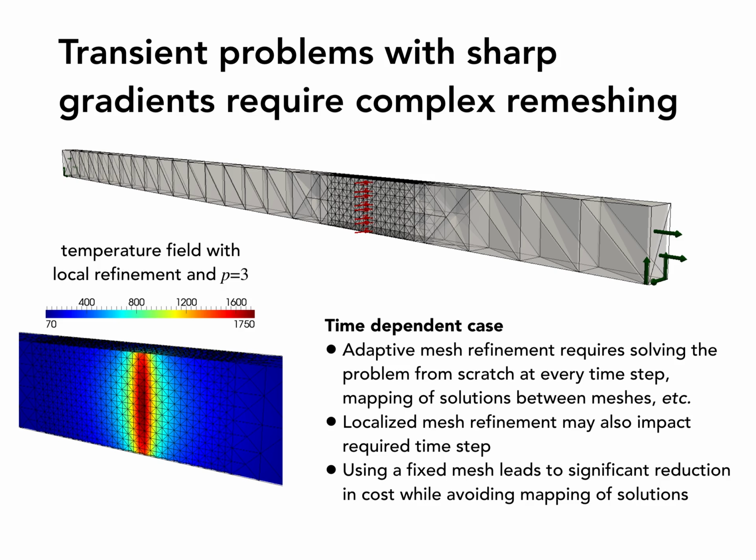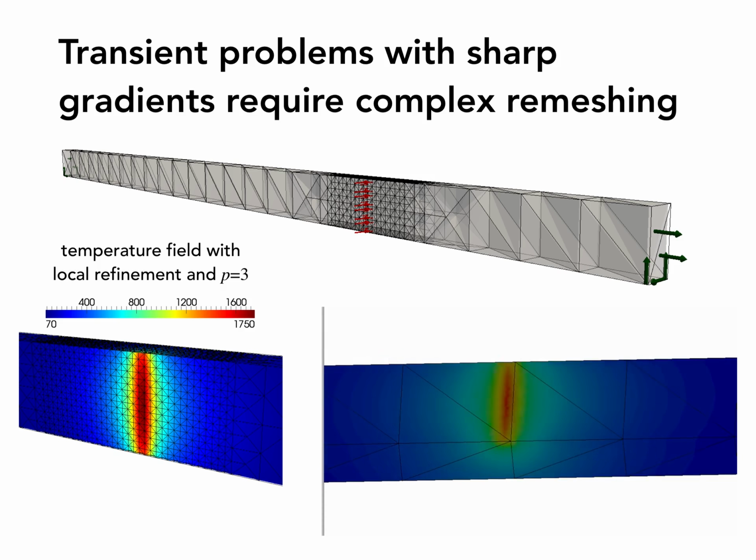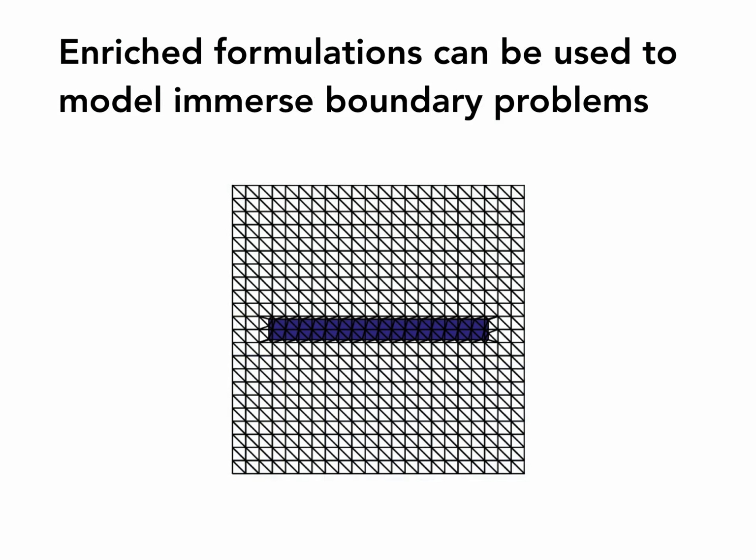But of course, if you're using Enriched FEM, you do not need the small meshing next to the application of heat, but just use a function that already captures that gradient, using a very coarse finite element mesh and still be able to capture the same solution. So these are some of the problems that I am actually interested in.